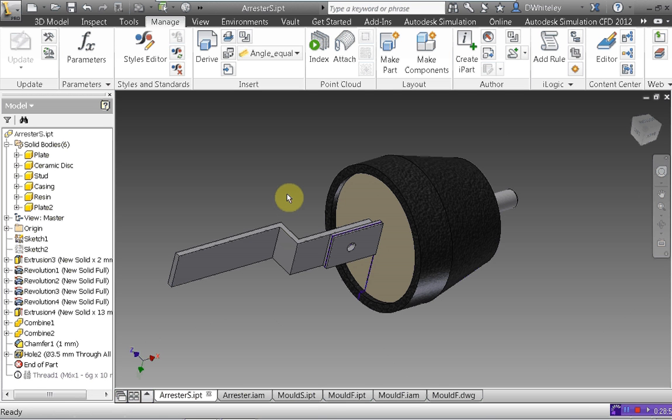Very, very fast. You're going to get the components out a lot quicker. And of course, there's a single part file that you go to change everything. You haven't got to remember to go to various parts within an assembly to update. And most importantly, of course, within assemblies, we're not using adaptive modeling, which can slow an assembly down. This is an extremely fast way of working.